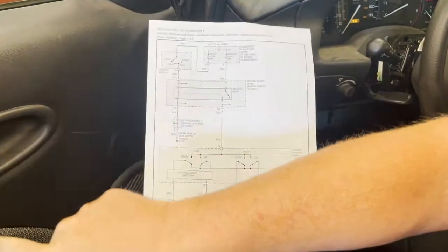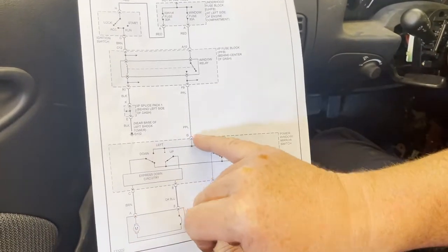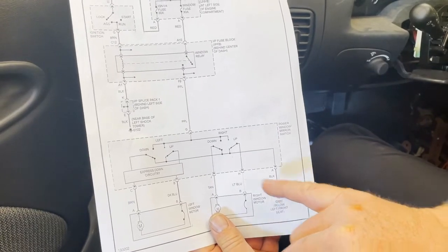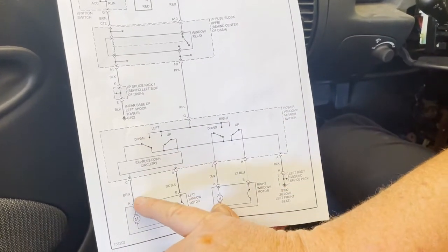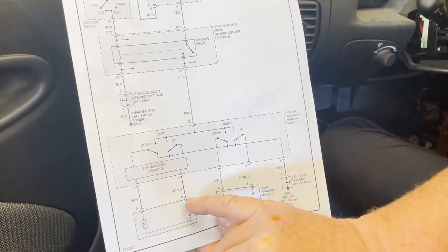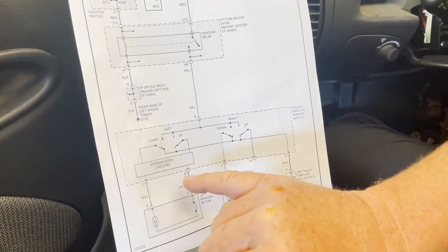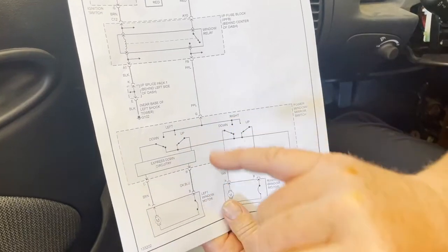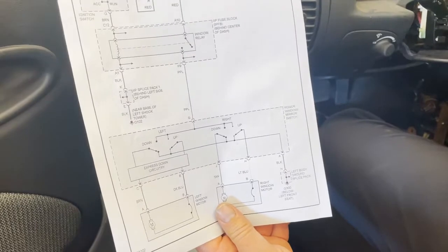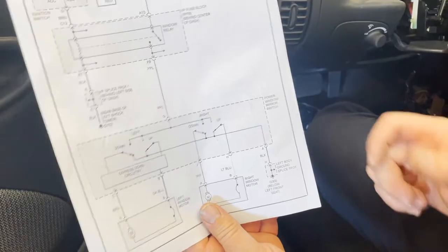Rolling. Before we get to the door panel, I want to recap. We checked power going to our switches on the purple wire. We checked ground on our black wire coming from the switches. We checked power going to the brown wire going down. And we checked power going to the dark blue wire going up. We had power here going up. We had power here going down. And they both have ground until you hit the switch. So we checked that circuit. Now we're going to check the window motor itself.